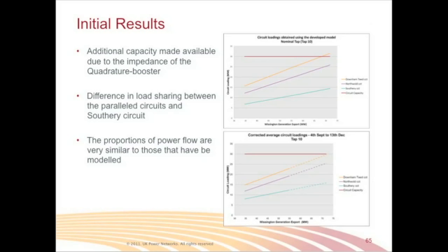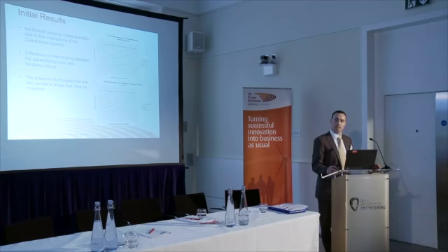Just to recap on some of the measurements that we've obtained from site. I mentioned earlier that the quad booster has spent most of its time at nominal position since it was put in place. Again, this is by virtue of the control system that we've deployed, which is exactly to deliver that. We don't want the quad boosters to tap unnecessarily. So the power flows through the two circuits, the Downham Market and the Norfolk, have been such that there has been no need to tap the quad booster, with only a few exceptions, which I'll go into on my next slide.